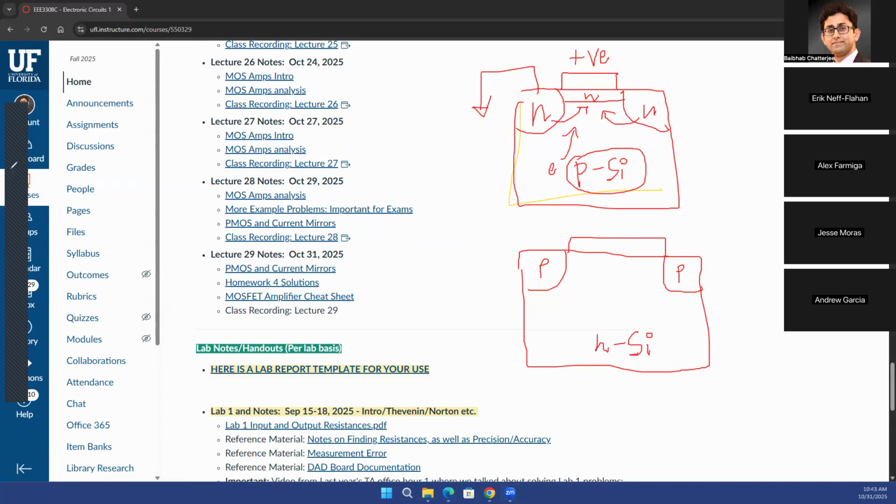So you're going to apply a negative voltage at the gate. But what that also means, in a similar manner as NMOSes, the negative voltage at the gate really means a negative VGS. The gate to source voltage will be negative. And for the NMOS, what you wanted to have was this VGS greater than VT, so that the transistor is on. And then the second condition that you wanted for the transistor to be in active or in the saturation region is that your VDS, the drain to source voltage, needed to be greater than V overdrive. And remember that V overdrive is nothing but VGS minus VT.